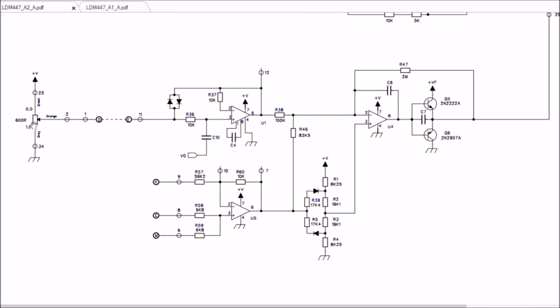So here we have the feedback potentiometer. We can see that there is a voltage follower. We can see that the wiper of the feedback potentiometer is not connected to the servo control system here, but it is connected to one terminal of the connector. So we should provide here a link between terminals D and E. I don't know why they have separated the feedback potentiometer from this voltage follower.